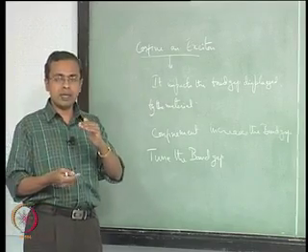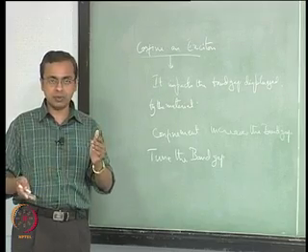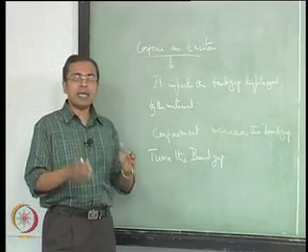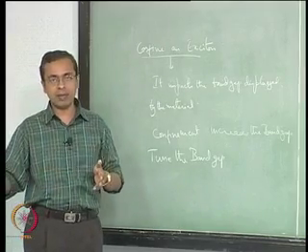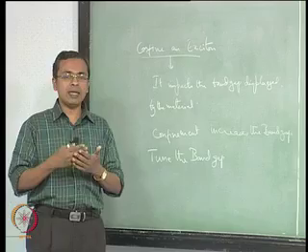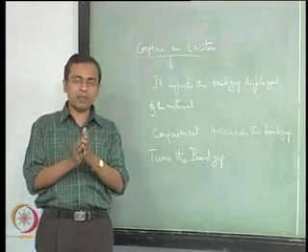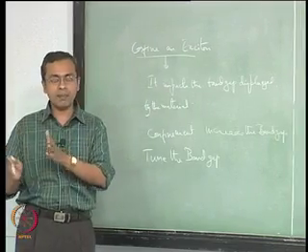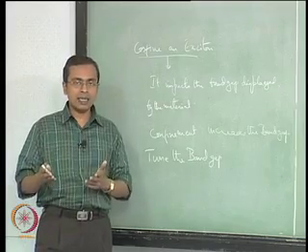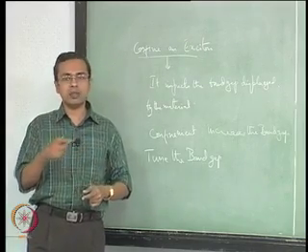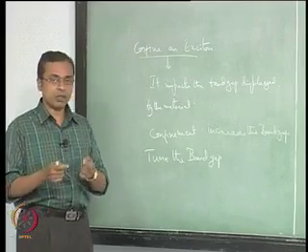So you can have a set of particles which are different from the bulk band gap, but they have a distinct band gap associated with them. You can get a variety of different band gaps with the exact same chemical composition. So you now have the possibility where you can put together a component with pieces, each of which has a different band gap but has the same chemical composition. So you can eliminate dissimilar material contact but still have the property variation that you desire, so that you can get the component to work the way you wish for it to work.